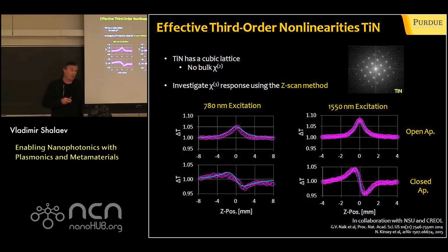So, nonlinear optics. Now we're coming toward nanophotonic circuitry. With titanium nitride, it can sustain high temperature. It means that it could sustain high intensities. But how large is the nonlinear response of these materials? Because for switching and this type of application, it's very important that it has a large nonlinear response. And it's known that gold has quite a large nonlinear susceptibility. To measure this, people use the so-called Z-scan.